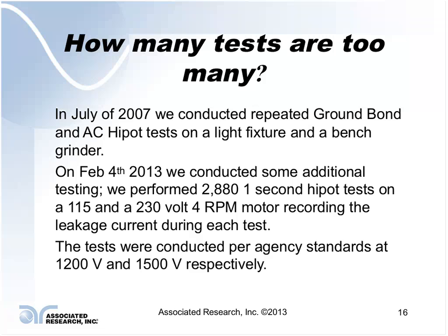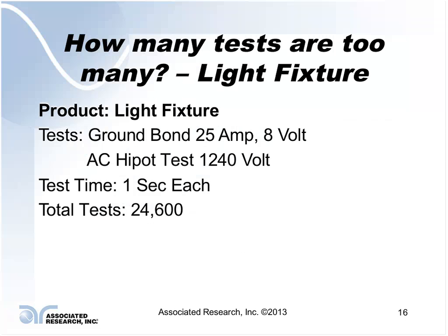We set it up with a timer, and we conducted 2,880 Hipot tests, one right after another, doing a 1-second test on each motor, and recorded leakage currents on these devices without a failure. Okay. We also did this on a light fixture. The light fixture had the most number of tests that we did on it.